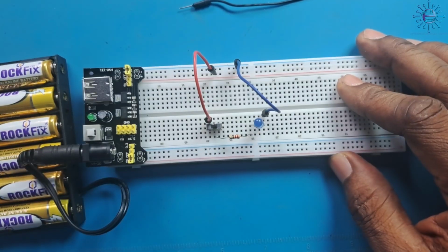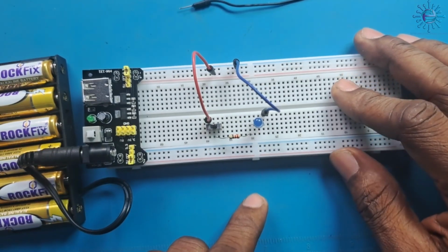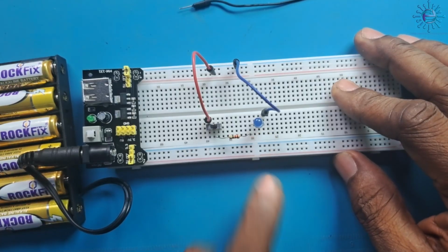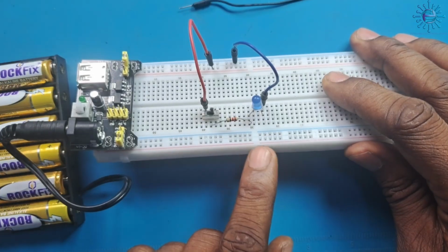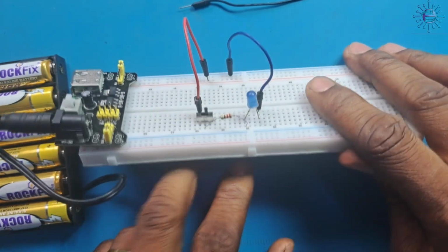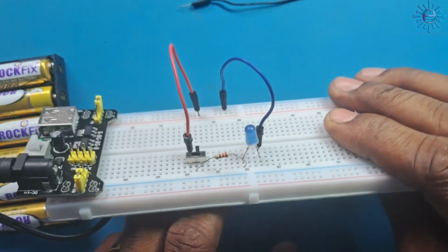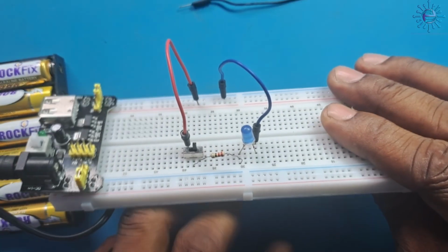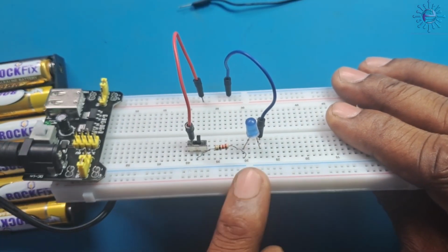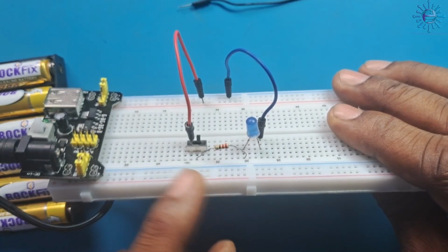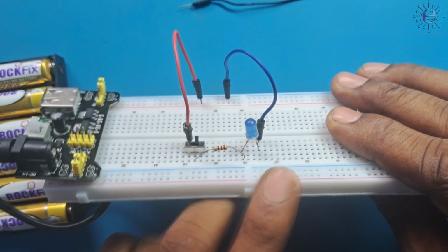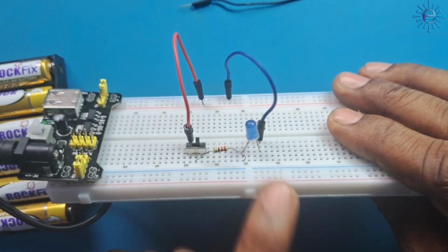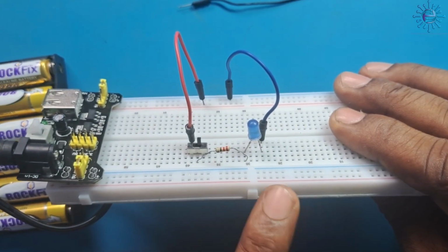One more thing you should know before we test the circuit. Anytime you are building a circuit that requires you to connect an LED, make sure you connect a resistor to that LED in series. A resistor helps to reduce or limit the amount of current that flows into an LED. If you don't connect a resistor to an LED in a circuit, excess current may flow into that LED and damage it.